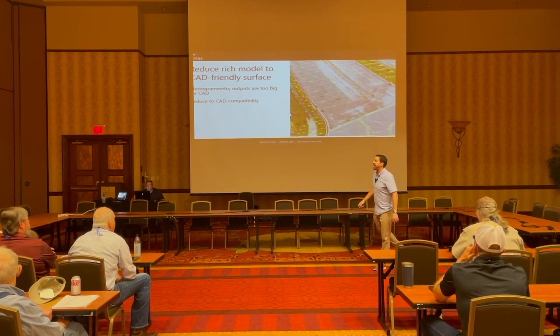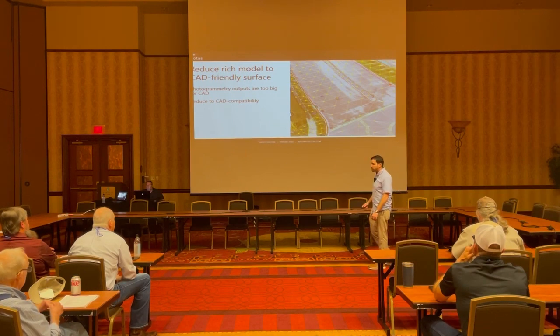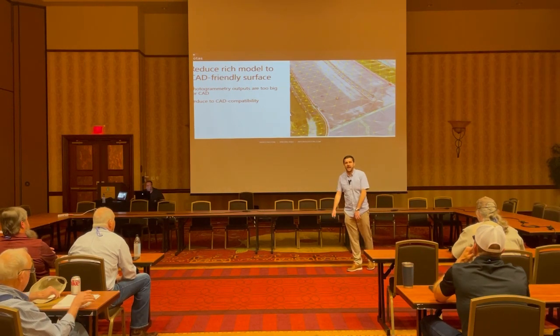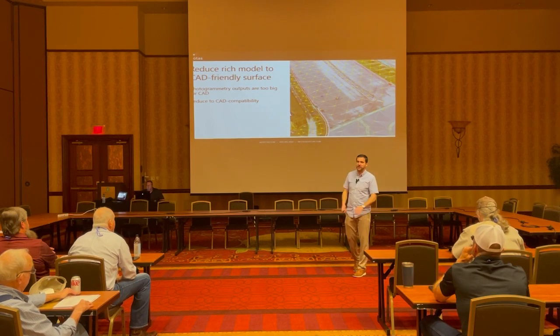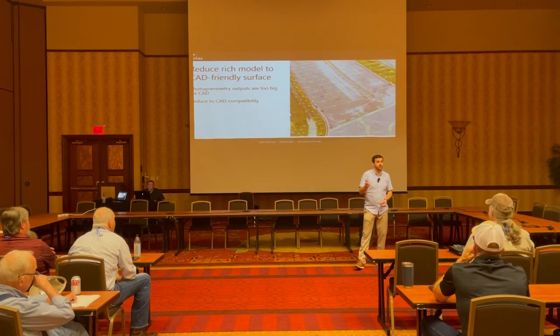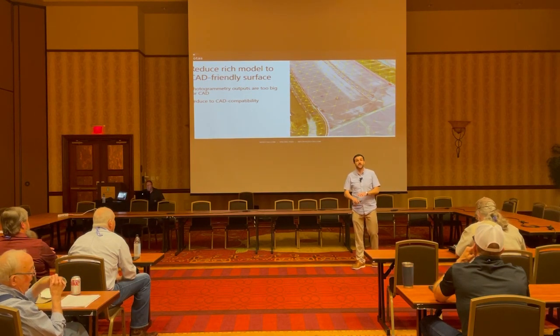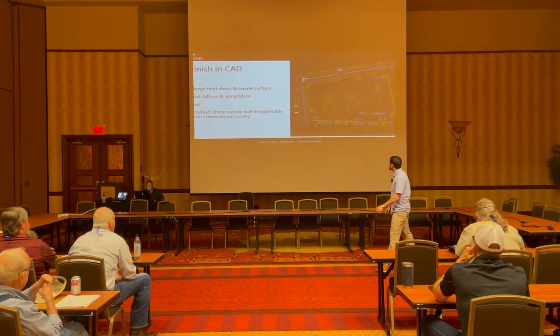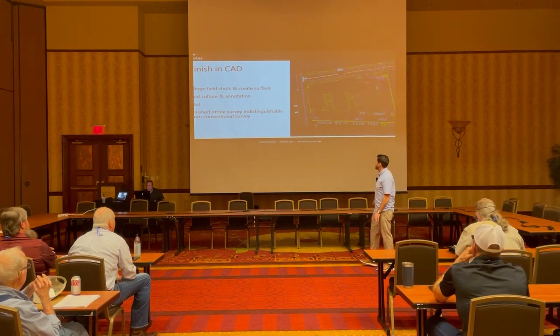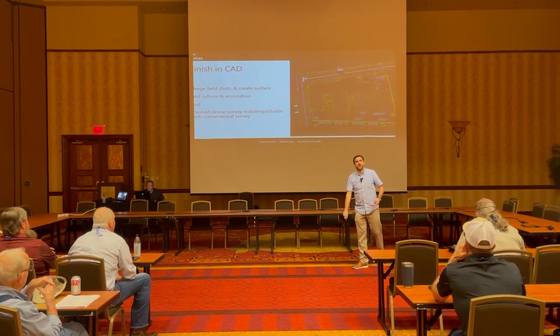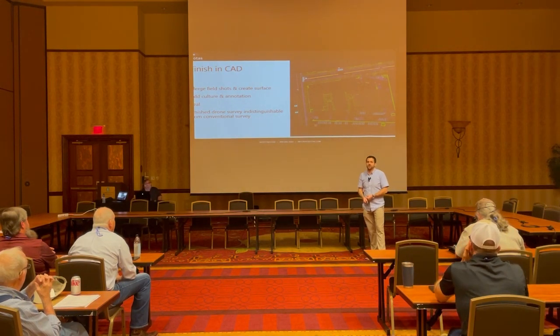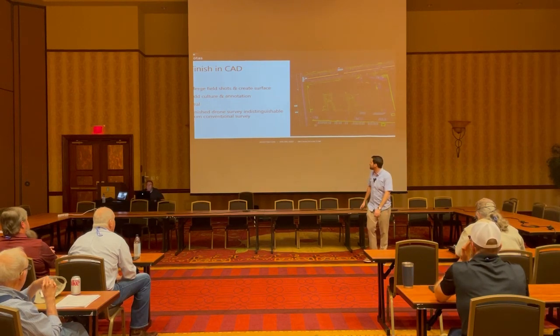It's extracting all of that data from those rich deliverables to reduce it to CAD compatibility, which again, Civil 3D, if anyone's ever tried to put a full resolution orthophoto or point cloud into Civil 3D, I mean, it just gives up and quits. So you got to do something in between. And then, like I said, finishing it into CAD, merging your field shots, creating a tin surface, turning that tin surface into contours, things like that.